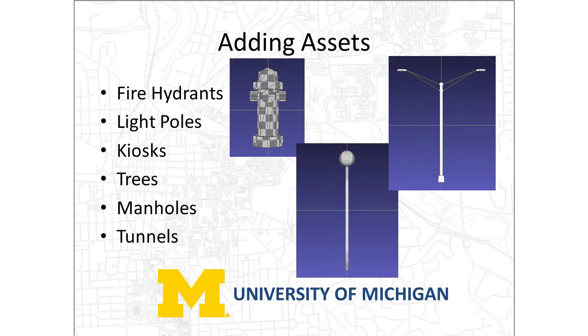When you're putting in a height, because all of our poles have heights to them, we can be data driven as far as how high it is on the model. Not only are you going to change the height, but the OBJ file, when you expand it, is also going to expand the width. So for each family of heights that you're going to have, you need to create a different OBJ for that height so that the spans of your arms are in relative size to what you're looking for. These are typically in the 11-foot range. They vary, some are 20, some are 30s. We've got some that are in the 40 range, and when we get to field lights, they go up to the 60-foot range. So you've got to make different OBJ models for that.